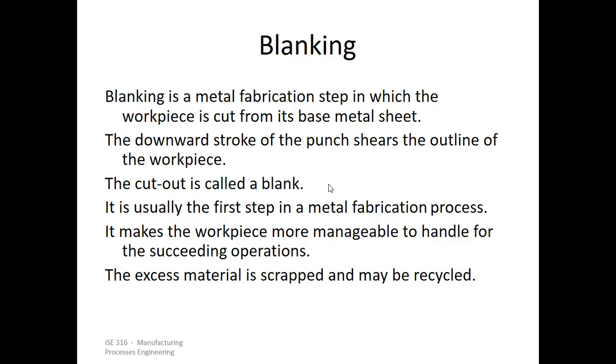So as for blanking, it's a metal fabrication step in which the workpiece is cut from its base metal sheet, right? The scrap, the strip, basically. The downward stroke of the punch shears the outline of the piece, right? Basically, shearing, that's the dominant mode of deformation that is happening here. That is yielding the result. So the downward stroke of the punch shears the outline of the workpiece, as we know. The outline is basically where the punch and the sheet are contacting.